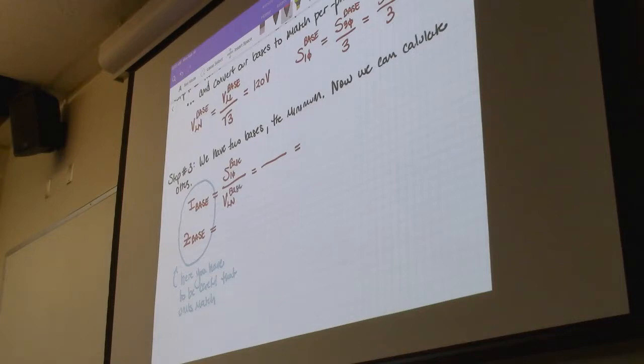So the bases, the base values, that's the things that we're gonna relate everything to when we do the curve. You'll see there's a second step to this. The final step is to actually take those values that were given to us, the actual values, and put them in terms of the bases. So when we do a per unit problem, the first thing we need to do is make sure to come up with a set of 4 coherent bases. And that's what we're doing. The bases that convert to one another appropriately using the line to line, line to neutral, 3 phase, 1 phase, V to Z, all that type of stuff.